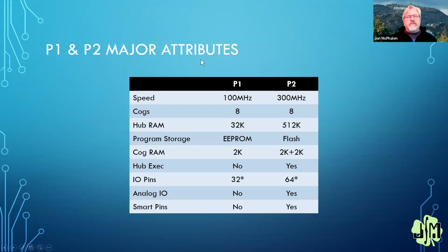With flash, there are rules about that, so it's a little trickier to write. Thankfully, that little RTC module that we're using on this project has an EEPROM on it. So next week, for saving our settings, so when we boot up the thing comes back where you left it, I'm going to use the EEPROM until we've sorted out a really nice flash driver that's just as easy to use.